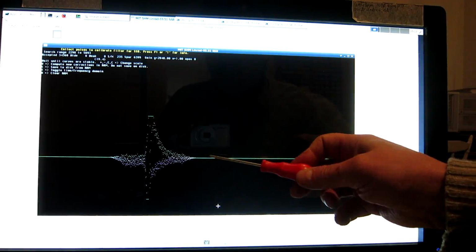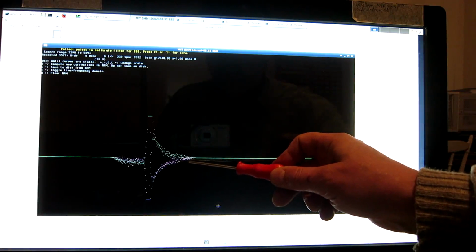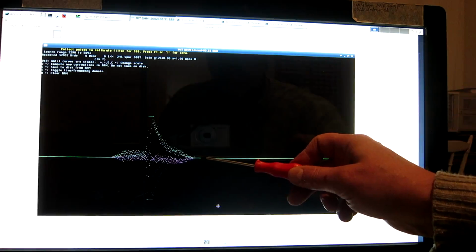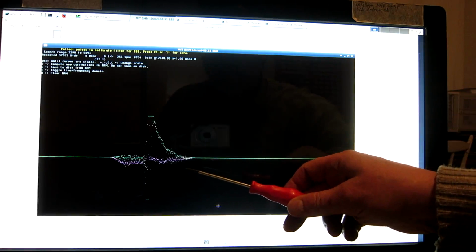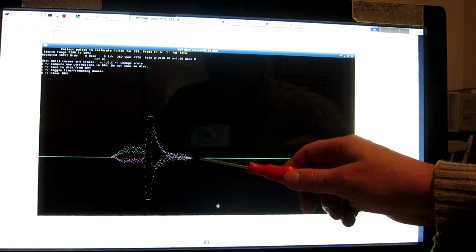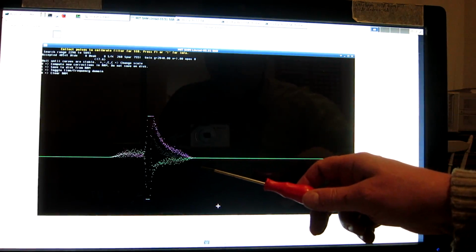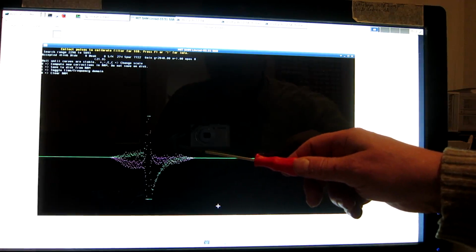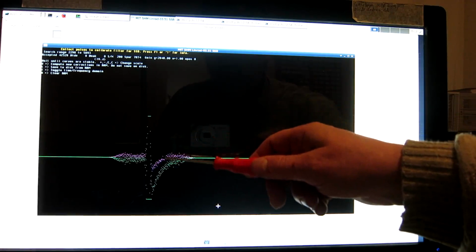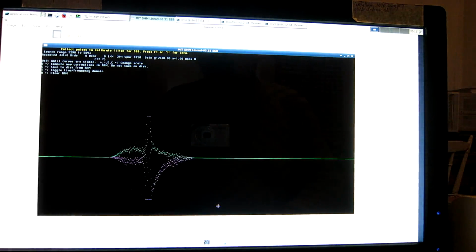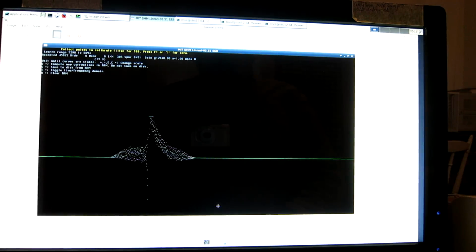And then in the same fashion, the signal is brought down to 0 from here to here, also with a sine square function. That means that the effect of limiting the time range overlaps with the shapes of the pulses themselves, which are this form. This is not acceptable. With this hardware, one has to use a lower pulse repetition frequency.